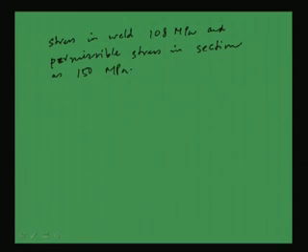So these are the data which have been given. Now we have to design this. Design means we have to connect these channel sections through one gusset plate, so that the maximum load which can be carried by the channel section can also be carried by the connections.